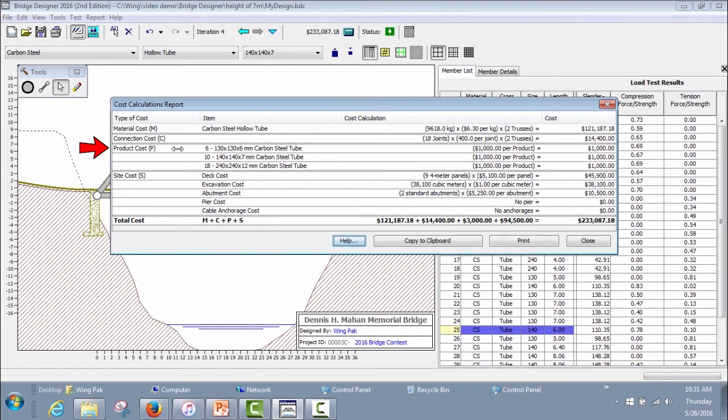Again, there's a logic behind this. Imagine you're a steel fabricator, and let's say that you have a job whereby the engineer, the technician, really went crazy and overboard. He decided to optimize all the members in the bridge so that each one is different and that each one is just on the verge of failing. He's going to use a different size of tube or bar for each one of the members in his bridge. As a fabricator, think of all the extra work you have to do. You have to order all this extra material. From each batch of material, you're probably going to use only a few meters of material. The rest of the material is probably just going to sit in your shop waiting for another job in which you can use that material. Without any doubt, this is going to cut into your profit margin and your productivity.